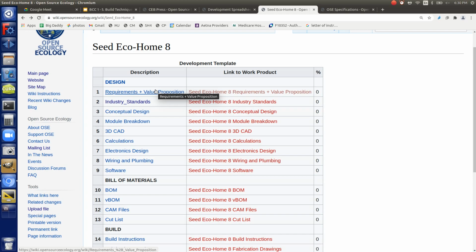So if you work out the requirement, you can say, well, the modules must be 4 feet wide and use standard dimensional lumber pre-cut studs. Well, then you've already literally given me a bill of materials, which I go to Menards for. I know I have to get a pre-cut stud of some sort. Or if it's 4 foot wide, I have identified that the top and bottom members in our modules are 4 feet long, so in my bill of materials, I better have a count of some 4 foot long stud members and things like that.